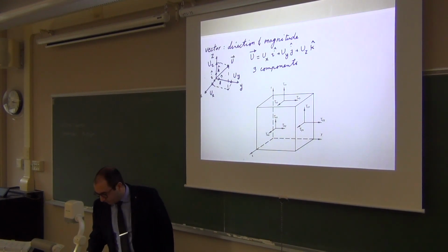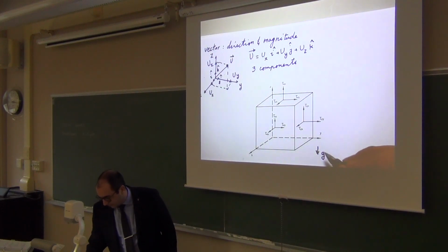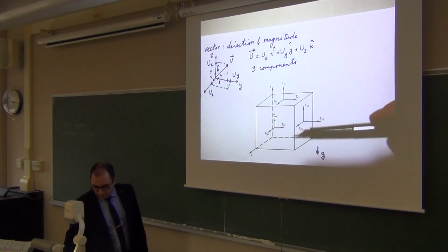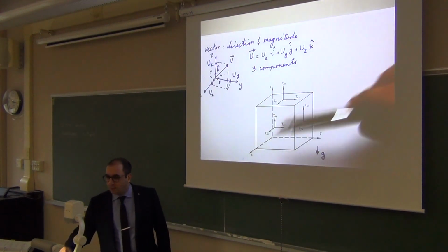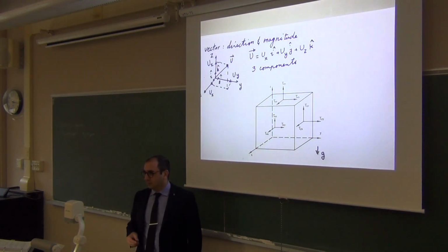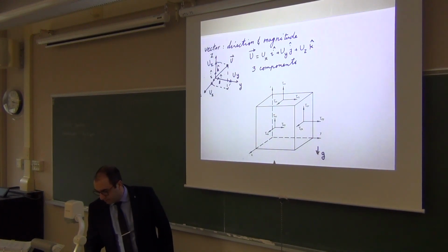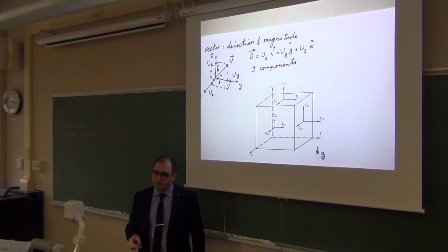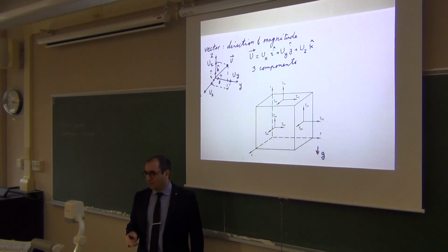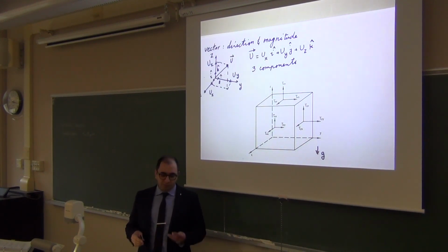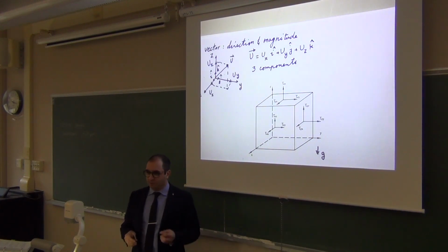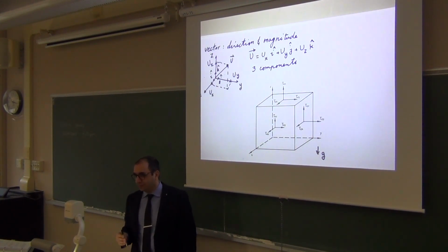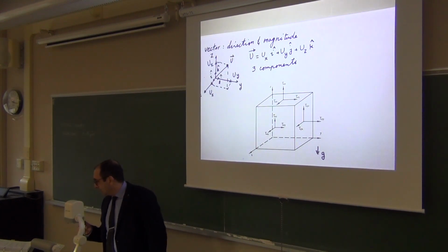Let's say you have the same control volume of fluid that we were talking about. This control volume has actually 6 faces or planes that make contact with the outside world. So there are actually 9 pieces of information that I need to tell me what happens at that surface as the control volume makes contact with the outside world. And I need to know all 9 pieces to be able to know what happens to the property of interest in the control volume. It could be momentum, which is the case at the moment, but it could be other things as well.